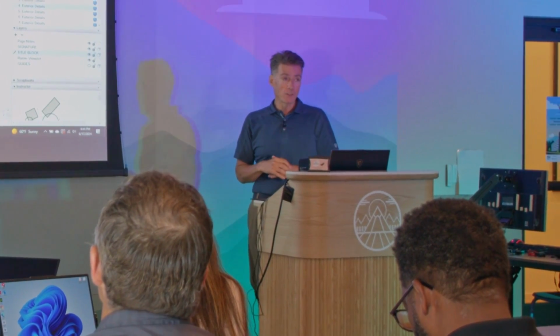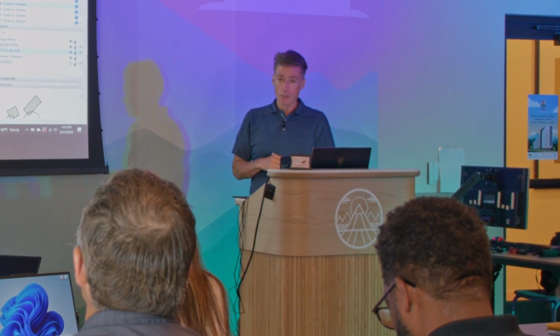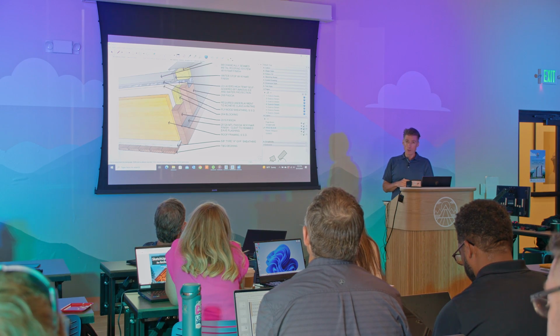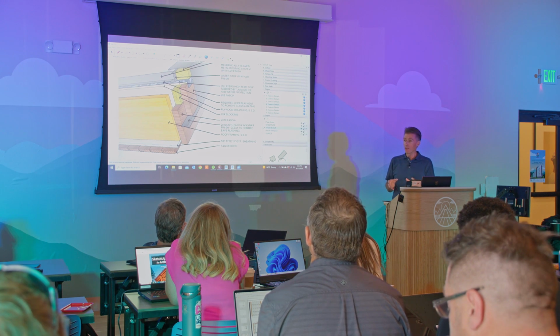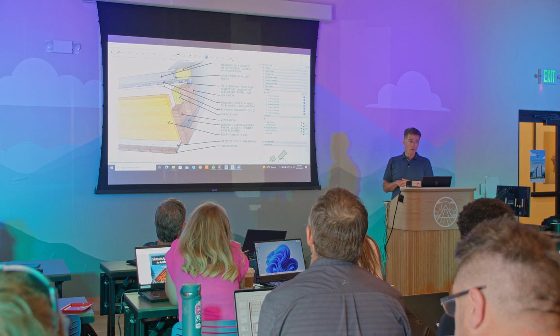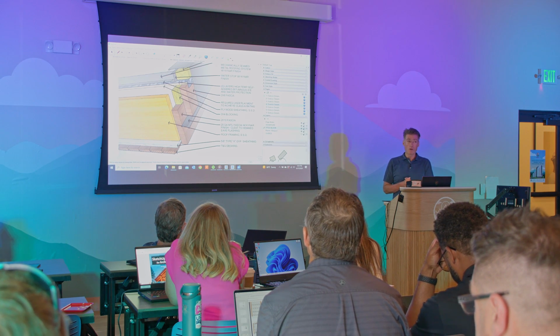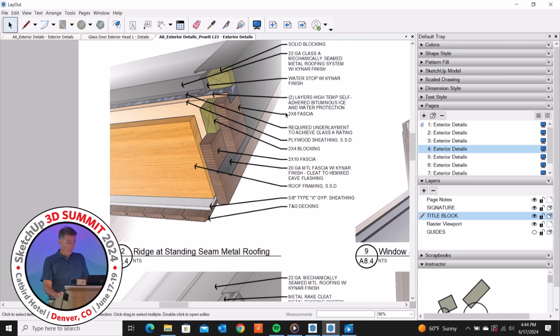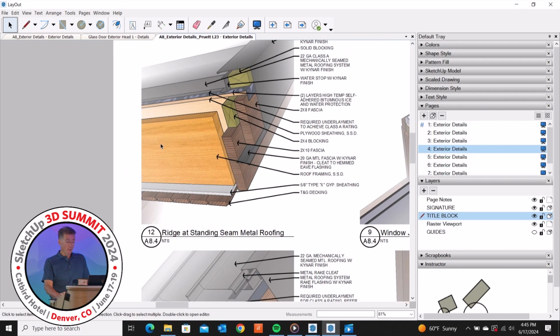You'll notice we have no venting. We don't vent our roofs at all. We use closed cell foam. And we use a combination of 5 inches of closed cell foam, which gets us roughly R35, technically R34.5. And then we put unfaced bats below that at R19. And those systems have been working pretty well. Gives us a really good R value on our roofs, over 50. And we use all engineered framing for our roofs. They're all done with LVLs.